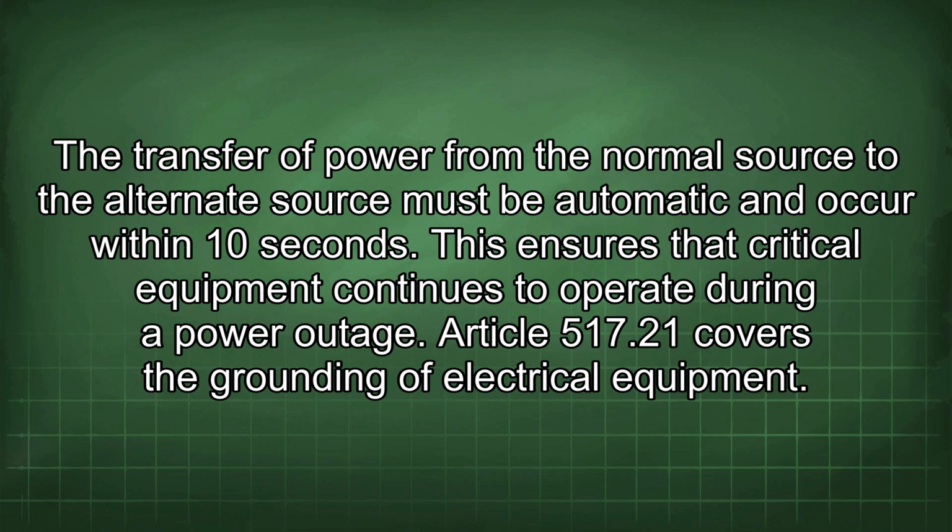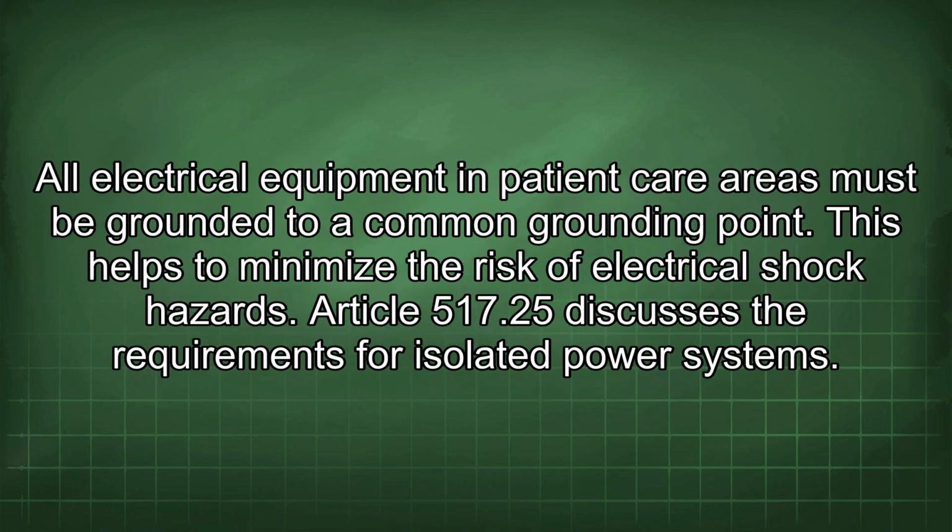Article 517.21 covers the grounding of electrical equipment. All electrical equipment in patient care areas must be grounded to a common grounding point. This helps to minimize the risk of electrical shock hazards.